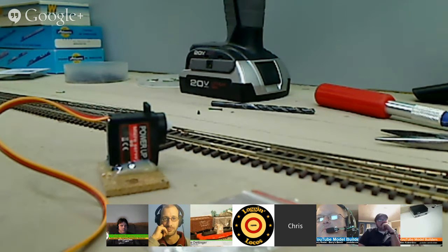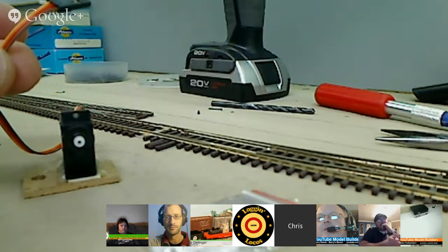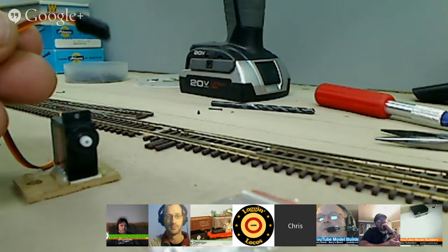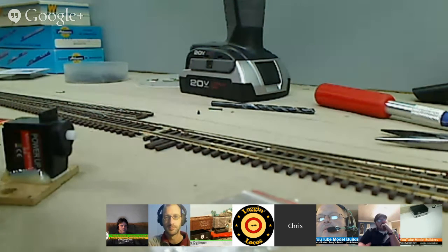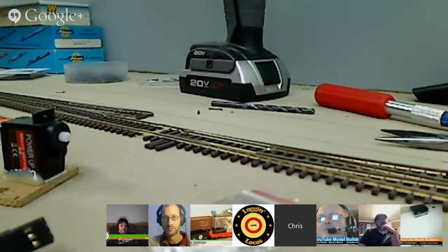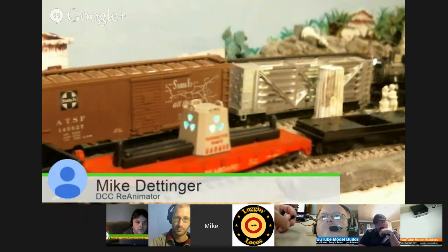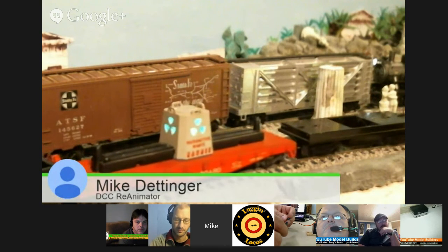Yeah, when it comes to the leads, there's actually 2 different kinds. There's the ones that have the yellow, brown, red. And then there's, let me grab a sample, a white, red, and black lead. Yeah, that's Hi-Tec. And then yellow, brown, and red is Futaba. So basically red's the same in both, and yellow equals white, and brown equals black.